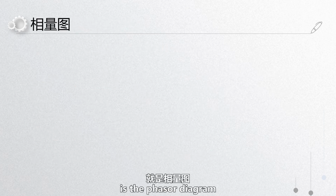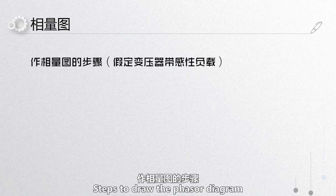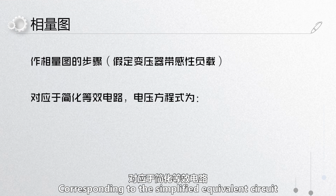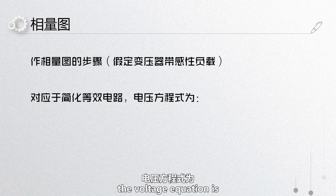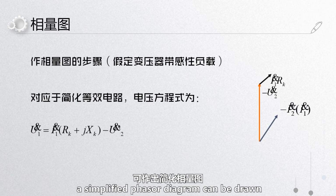Next is the phasor diagram. We will create a simplified phasor diagram. Steps to draw the phasor diagram: assume the transformer has an inductive load corresponding to the simplified equivalent circuit. The voltage equation is U1 equals I1 times (Rk plus j Xk) minus U2 prime. According to the equation, a simplified phasor diagram can be drawn.